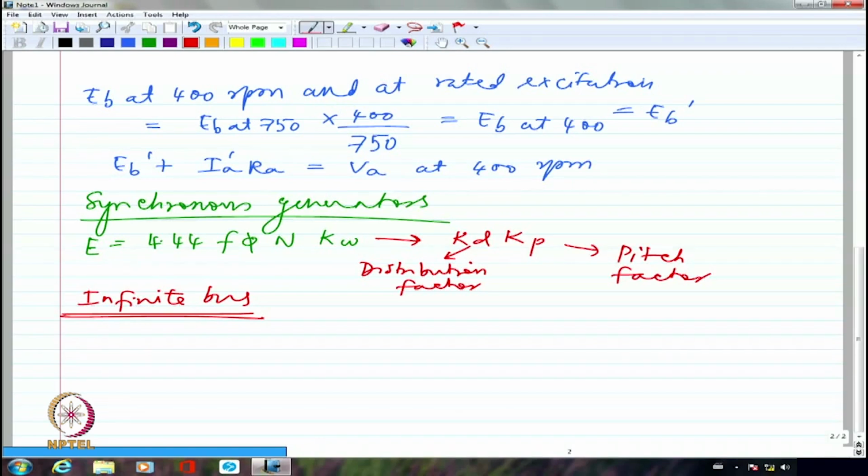It will make a difference if I try to remove n number of generators completely from the grid. If I am going to have the grid supplying, let us say, X megawatts, and if I am going to remove so many generators corresponding to some Y megawatt, where Y is almost comparable with X, even 50% or something, then there will be a power imbalance. I hope you understand. There will be a huge power imbalance. What I am trying to say is, let us say X megawatt is my grid generation.